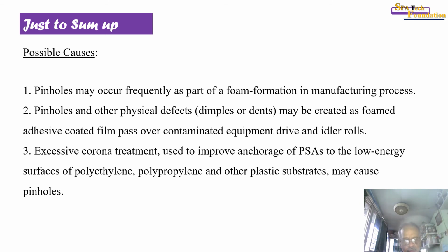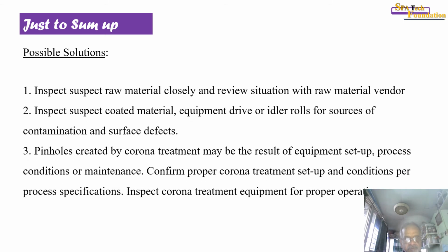it disturbs the coating. Possible solutions: inspect suspect raw material closely and review situation with raw material vendor or supplier. Inspect suspect coated material equipment drive or idler rolls for source of contamination and surface defect.